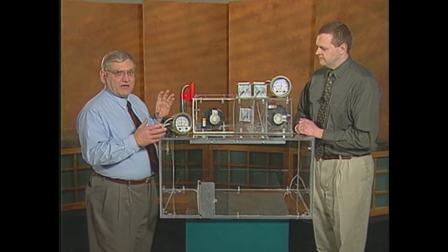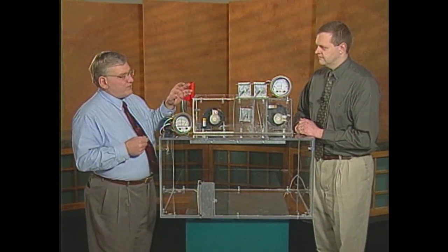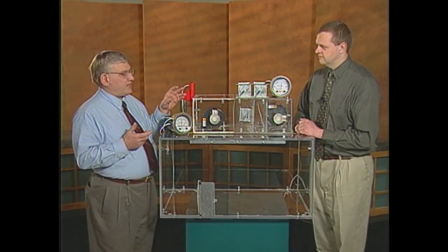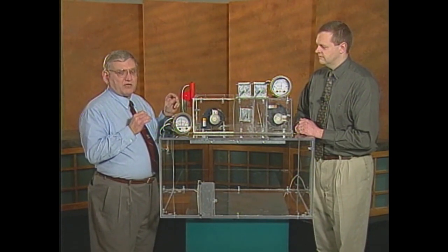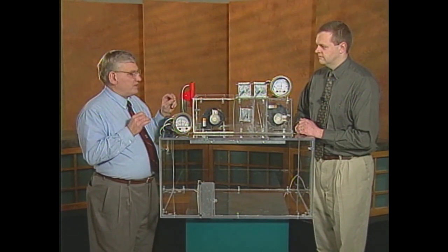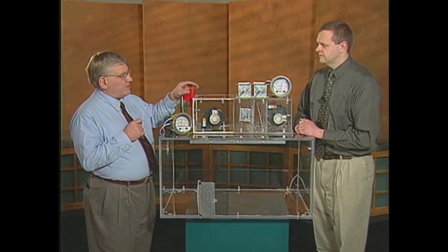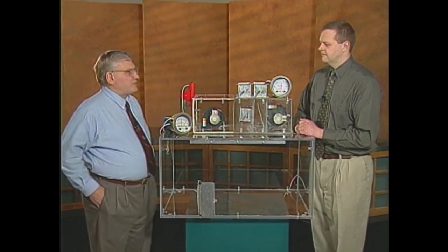Interactively, they all work together. You can see there's 4 individual control loops. Now, whenever you make a change to one of the 4 control loops in terms of flow, CFM, or static, you change the other 4. And the trick with this system is to make sure they all remain stable. John, could you start us out by changing us from a minimum outside air to full economizer outside air and describe the steps you do?